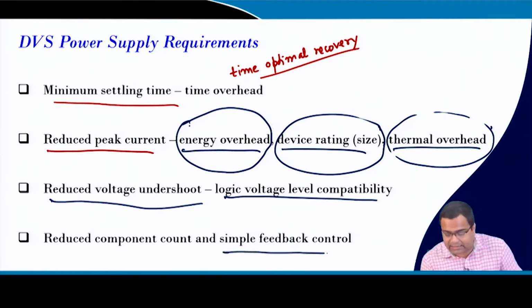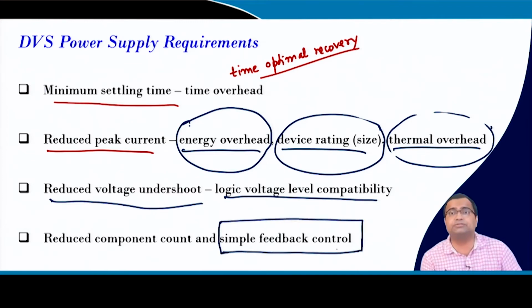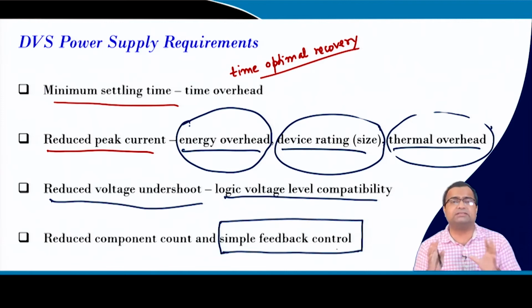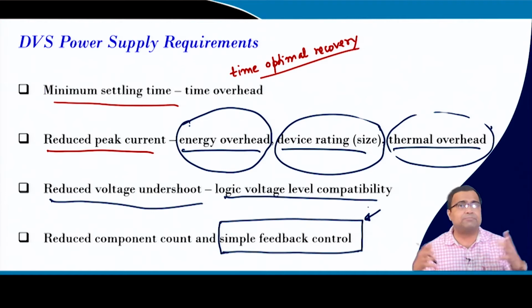And this part I think we have discussed: if we use our large signal tuning using a simple current mode control, that is a very simple technique that is used in many commercial products. By setting this controller tuning, you can get the fastest response. So, though digital control allows us to do very high performance control, we want to make our control simple, because ultimately it will be translated into silicon area and price.